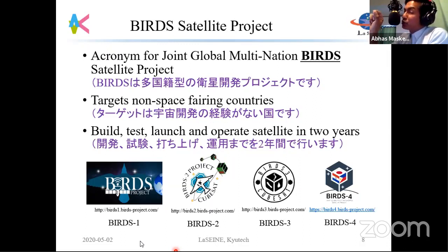You can also make sure that nothing is going under the oscillators. You can put in design rules, but design rules can only help you to a limited extent. But what I've seen with people who are much more experienced with PCB design, and when I took those courses, was they use a mix. They first route the most important lines the way they want, and then the less important ones are auto routed. So you can use a mix as well.